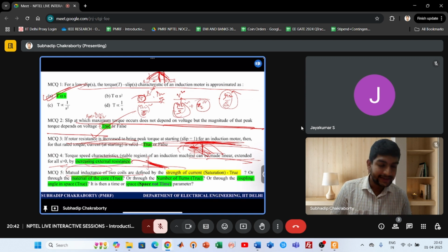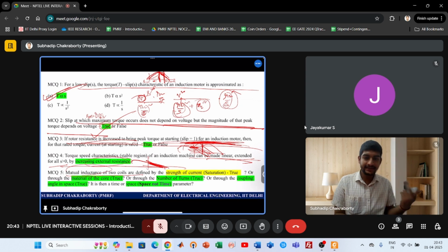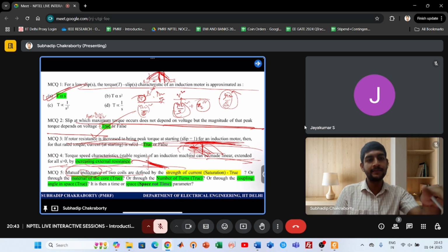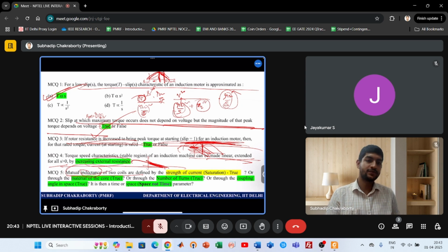But it also depends somehow on the current, because the permeance is also important for the coupling media. And the permeance is itself governed by the currents. We saw, na? Currents change the saturation, and then once it is saturated, mu reduces. We saw with saturation, mu reduces, becomes like air gap. So mutual inductance or inductance not only depends on the core properties but also on the current that the coils are bearing. Coil property, coil turns, number of turns, core material property, but core material property depends on the current of the coil. Because once saturated, the core material behaves like air gap.